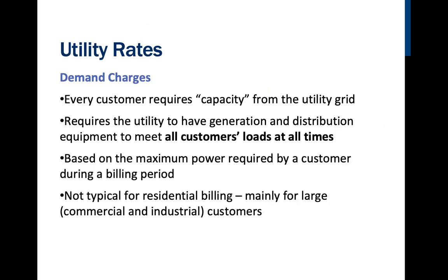Demand charges are typically something that is more of a commercial or industrial application. So this is not only the energy you consume over the month, but also the maximum power you draw in a certain amount of time, and that could be 5 minutes, 10 minutes, 15 minutes, whatever that max power draw. So power is just volts times amps, right? It's not energy over time. Power over time is energy.